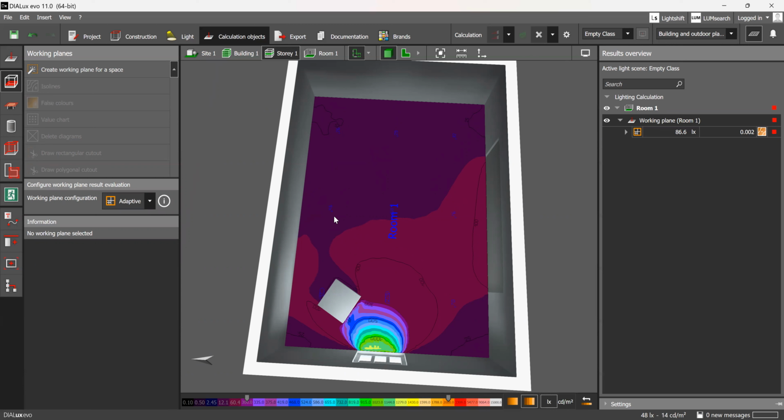Does measurement points have to match reality of what you measured in library? If you were going to calibrate a model, yes. For the assignment, you are not really asked to calibrate anything. So the simulation can just carry out for 1,000 points, right? But if you're calibrating something, you want to get, for example, one of those weather data files for today from International Airport, and then make sure that those grids are matching what you actually measured in reality, and make sure those numbers are matching, or at least fall within an acceptable bias. All right? Is that clear? Okay, perfect. So that's how you change the grid as well.